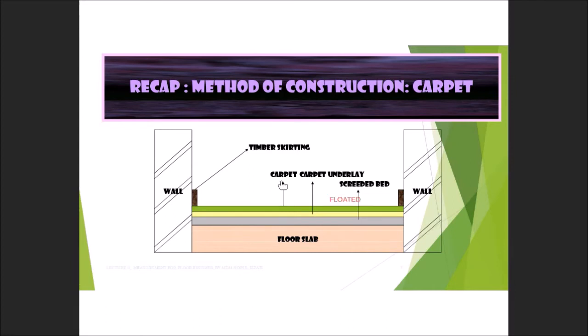Nowadays, we also have the carpet that not having this screeded bed. They only have carpet plus glue. Okay, so that is one type. Or maybe they have the carpet and carpet padded. They call this one as carpet padded, or that is actually come together. So that is also not having the screed. So you have to read the specification carefully before you start measurement.